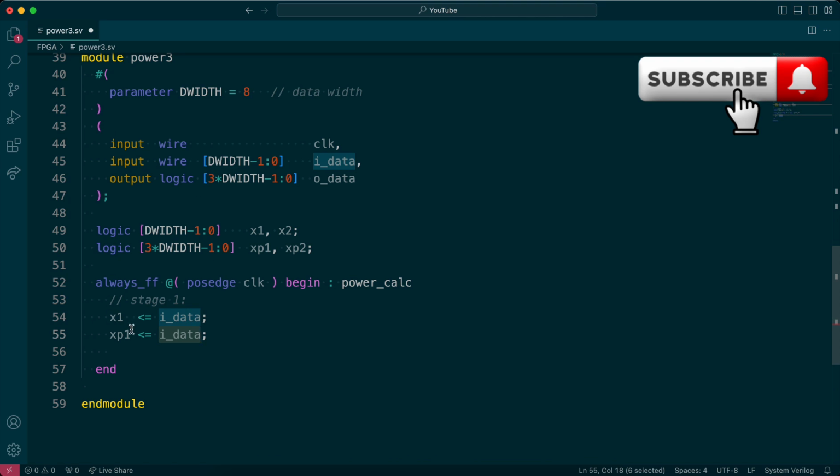So this is 3 times data width. If the data width is 8-bit, this is a 24-bit value, and this is an 8-bit value, and we're assigning an 8-bit value to a 24-bit value. A better practice would be just to zero pad the rest of it. But again, Vivado is smart enough to understand what you're doing here, and it only assigns this to the lower 8 bits of xp1 and keeps the other bits unchanged.